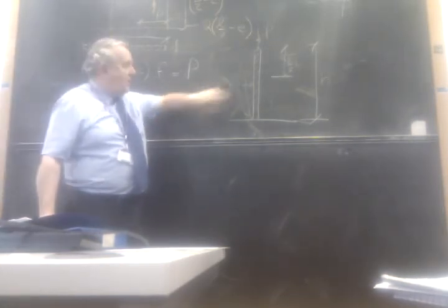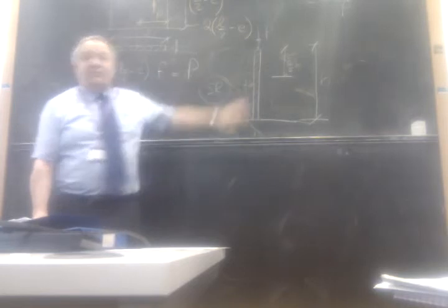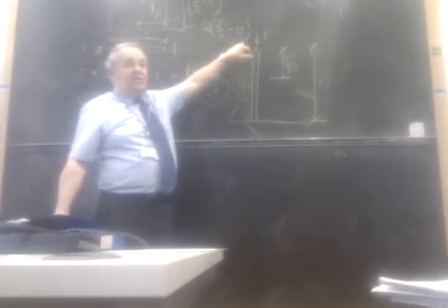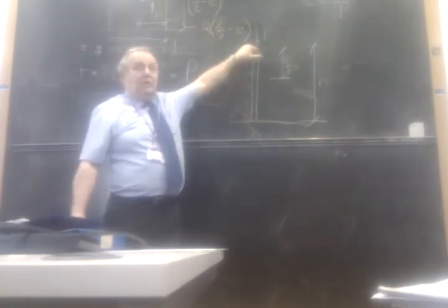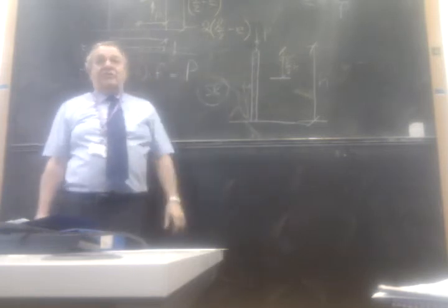But the effect that will come into play here will be the one due to slenderness. The bit due to slenderness is where the U comes in there. So we have no initial eccentricity at the top, so no eccentricity down the wall due to the applied load, only an eccentricity due to slenderness. So the EMK that sits in there will be 0. It's only the U effect you would need to consider. But you should check it in two places.